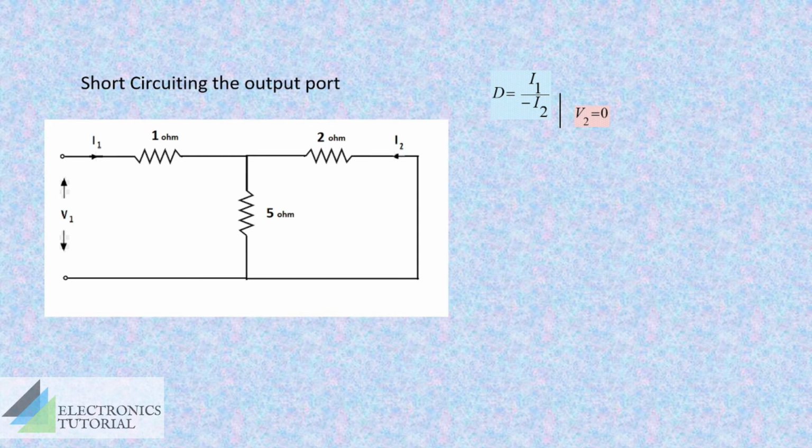I2 is equal to total current I1 into the resistance in the other branch, 5, divided by total resistance. Here, the current I2 is having a current direction opposite to that of I1. So, a negative sign is given. Now, the denominator has also become a term of I1. We can substitute this into the first equation.